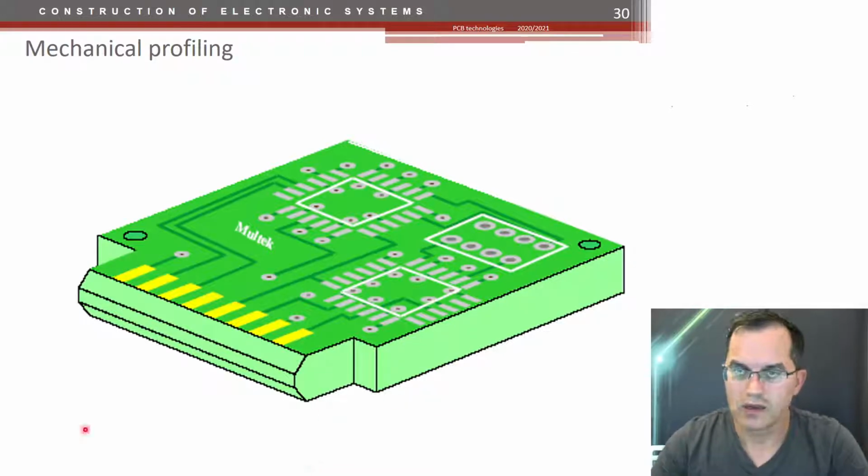Yeah, quite a lot of steps now, but quite a lot of additional steps, because the main focus here is to make metallized vias. And maybe just to make sure, the first simple process to make a single or even double layer PCB without metallized holes was just removing the extra copper with etchant. So etching the copper, and the thickness of the final copper is equal to the thickness of the copper at the beginning, because we just remove it.